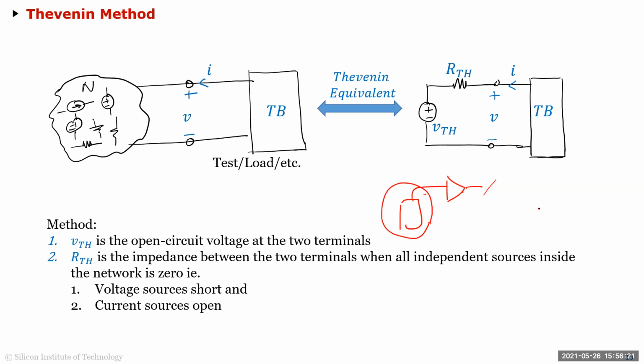So you have an amplifier which has an input and an output, and it usually has a very high input impedance. Rin is ideally infinite. So if your circuit is driving a very high impedance, then typically you want to do a Thevenin equivalent.